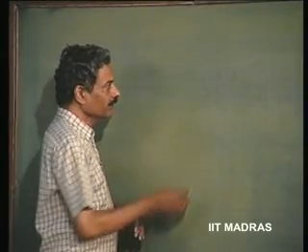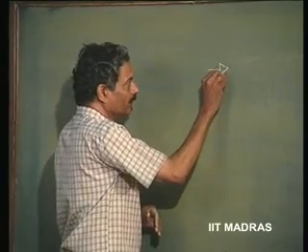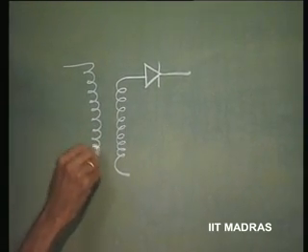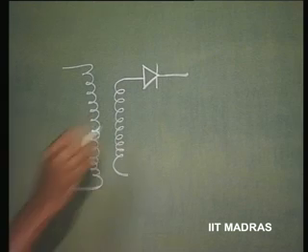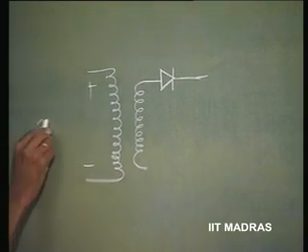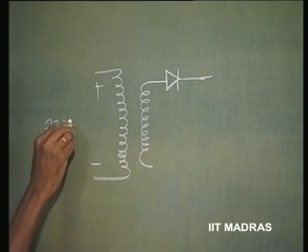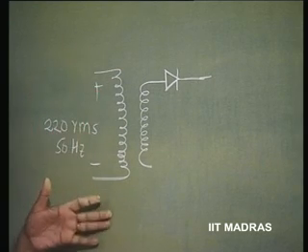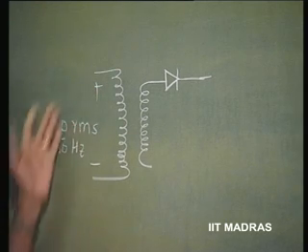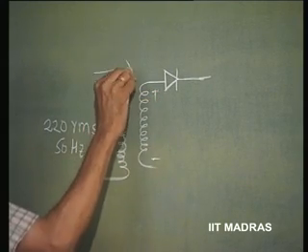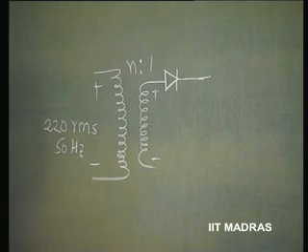So, we said by putting a diode and a transformer, let us say, this AC, which is, let us say in this case, 220 volts RMS, 50 hertz, let us say power line frequency, is applied here, and that is converted to something depending upon the turns ratio n is to 1.